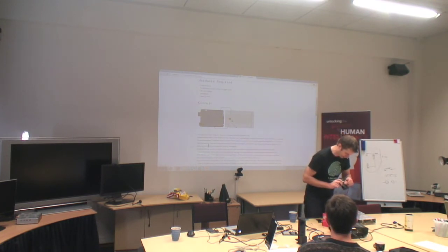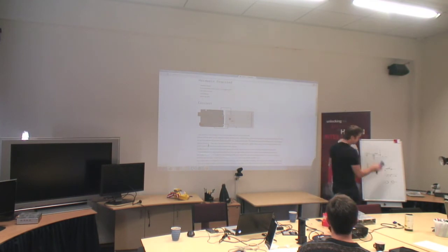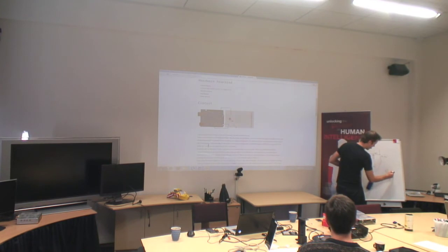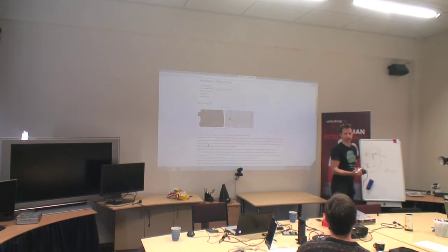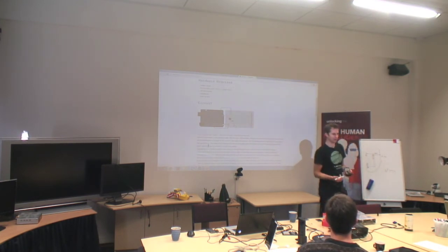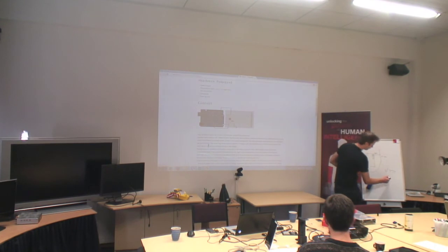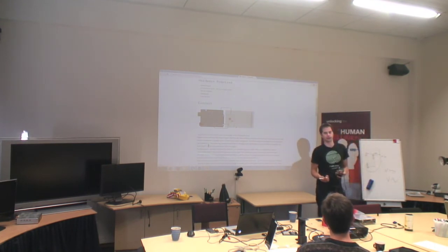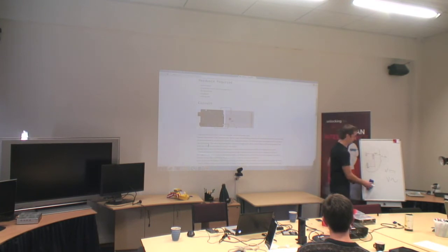Then this first one, V, with some lines on it. It's very small, so maybe I'll write the symbols up on the board. We have V, like that. So that's for measuring DC voltage. If you're ever wanting to measure voltage, that's the one you use. Then there's a V like that, which is analog voltage, which we're never going to be working with in this class, so you might as well just ignore that one.